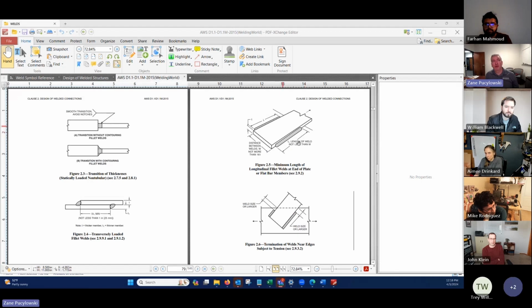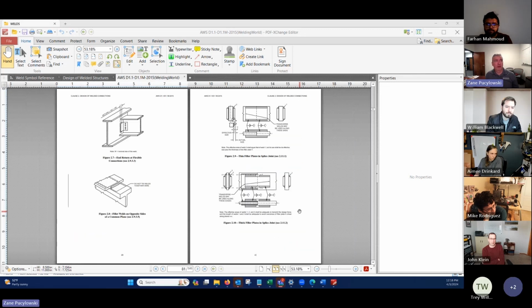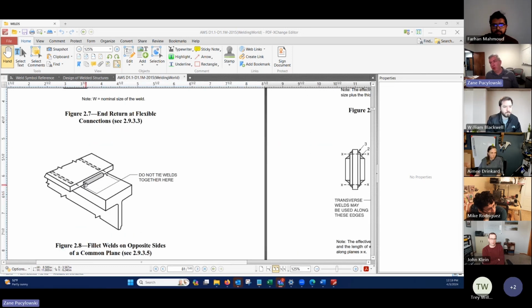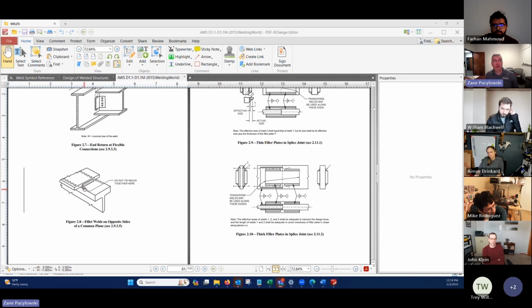So when you're welding something together, you don't always want to run out to the end, because that little corner right there creates a stress concentration. A lot of times if you slap a plate on the beam, you don't do a weld all around, especially if you've got fatigue loads, because you started a crack right here in this little corner. You'll put in your weld note a hold back: give me 4 inches of weld, 1 inch hold back on each end. That way I don't create a stress raiser or a stress concentration.